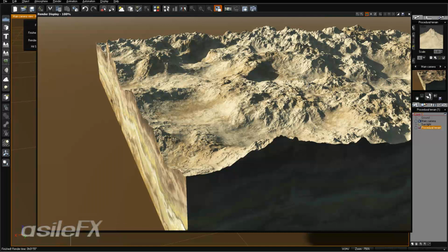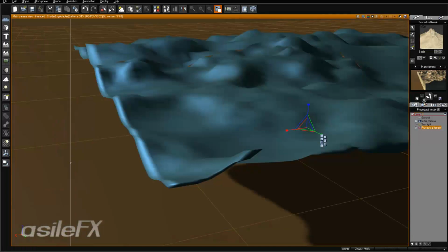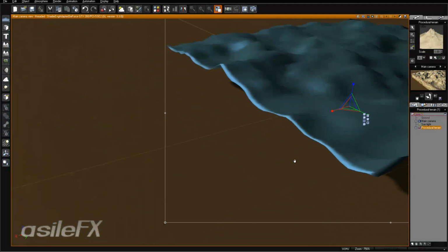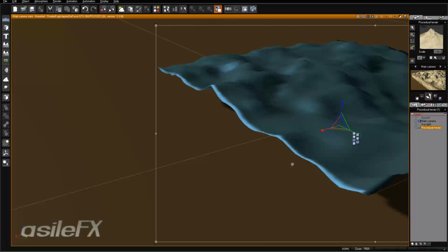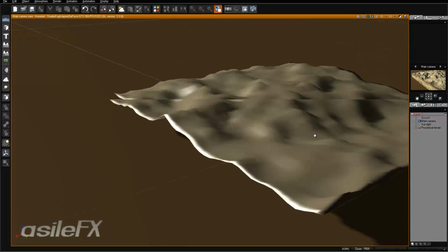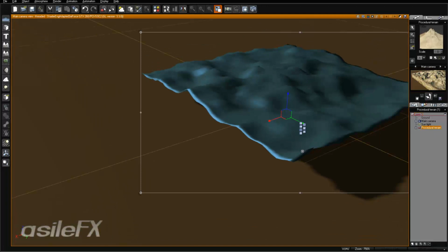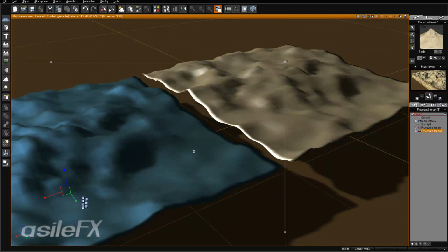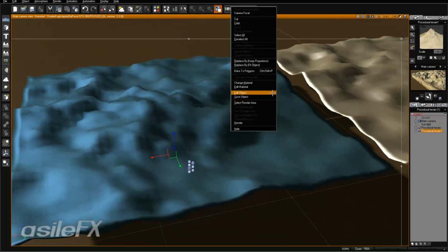So that's a very easy way to assign what you want to be on top of the terrain, and then have that cutout portion be a different material. Before, I talked about the procedure for a standard terrain, because we don't have the height information. What I'm going to take is this terrain. If you hold down Alt on the keyboard and select the gizmo for the movement on the X and move that over, it's going to create a duplicate of the terrain.